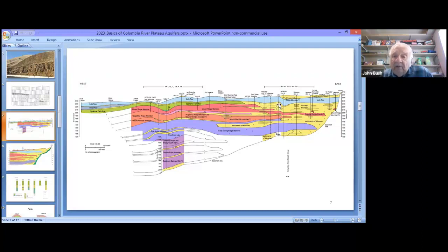The top part through the upper aquifer is required to be cased off if you are getting water from the lower aquifer, because both states, Idaho and Washington, have a law prohibiting the interchange of major aquifer systems. So the top part here in this well is cased off. The inner bed there where the cursor is at now is cased off.